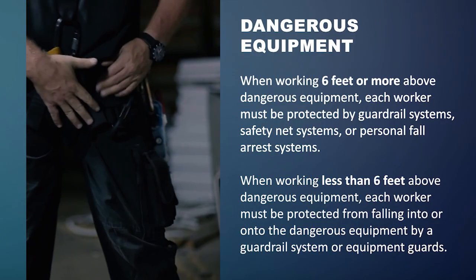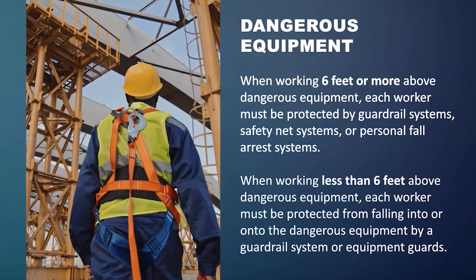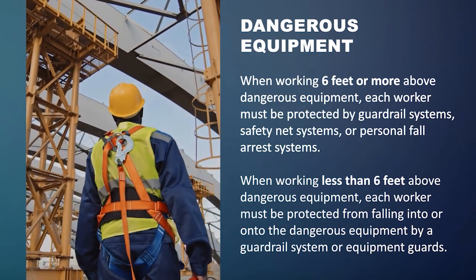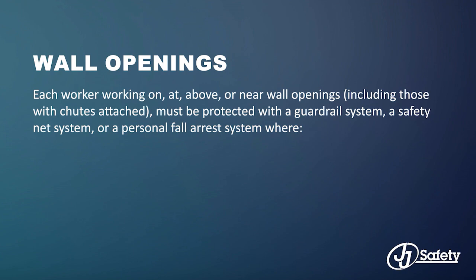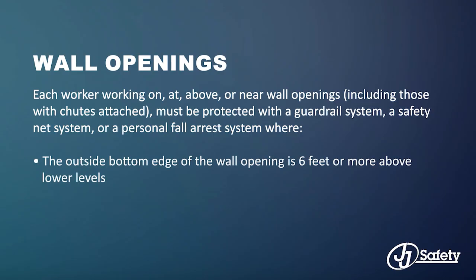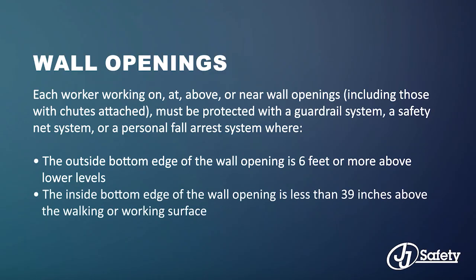When working less than 6 feet above dangerous equipment, each worker must be protected from falling into or onto the dangerous equipment by guardrail system or equipment guards. Each worker working on, at, or above, or near wall openings must be protected with the guardrail systems, a safety net system, or personal fall arrest systems, where the outside bottom edge of the wall opening is 6 feet or more above the lower levels, and the inside bottom edge of the wall opening is less than 39 inches above the walking or working surface.